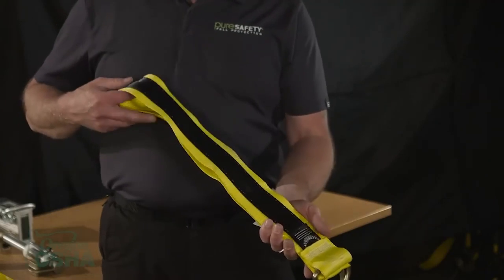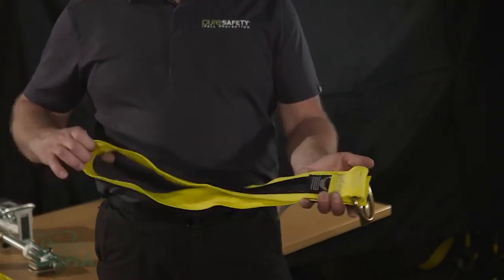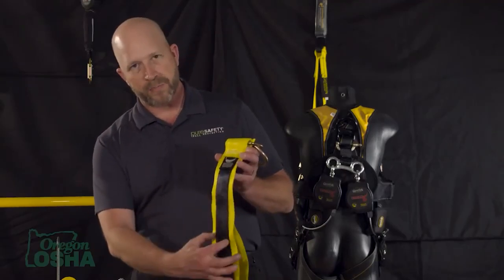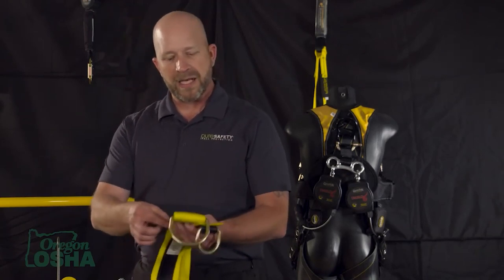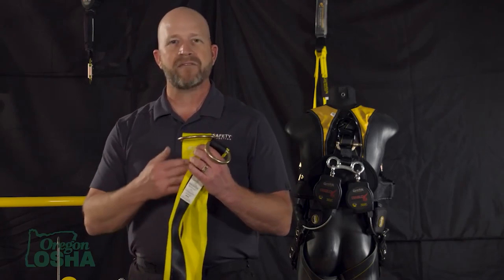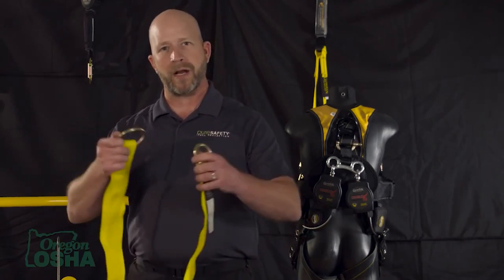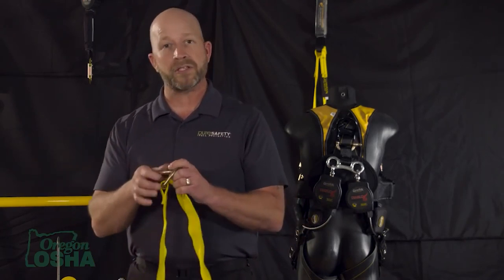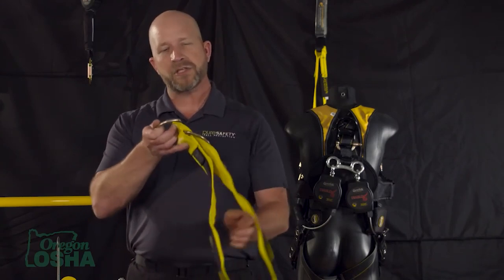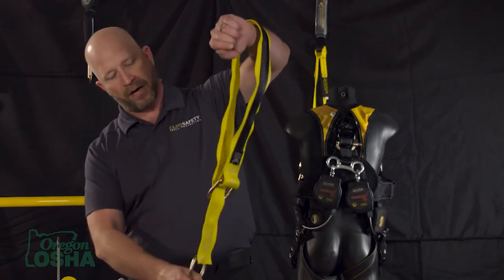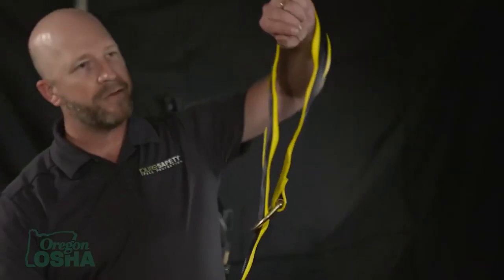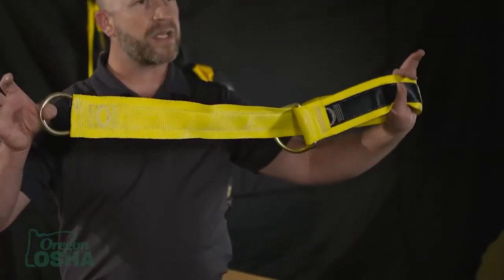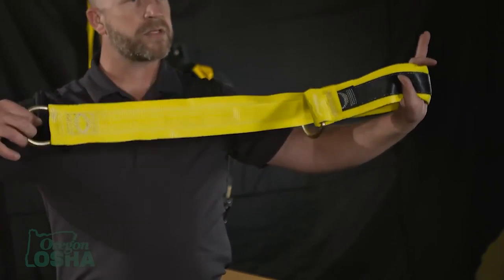The nice thing about these is that they're very easy to install. The structural part is this black part, where you can see the webbing is sewn in and the D-rings are. And the yellow backer part is a softener. So as you're wrapping it around something that has sharp or burred edges in the construction world, you just choke it back around whatever anchor it is, and then you can hang your retractable from there. If you're using a horizontal lifeline, in many cases they can be used vertically this way, putting some tension in.